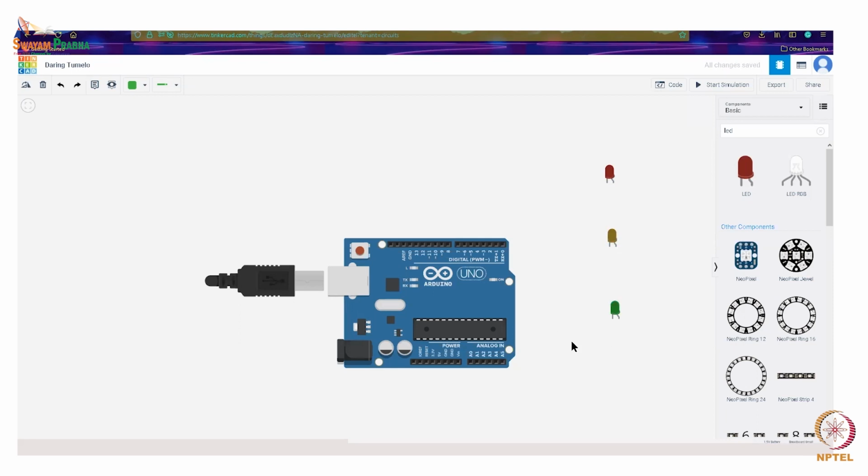So in Arduino, we have two sets of pins. One is the analog pins. The second one are the digital pins. Out of the digital pins, we have six PWM modulated pins. So the PWM pins are basically used for controlling servo motors, the ones which use the width of the pulse as a signal for actuation. So right now our LEDs are a digital kind of a device. So this will be accepting a high and a low value. So for that purpose, we'll be just using the digital pins for our current instance.